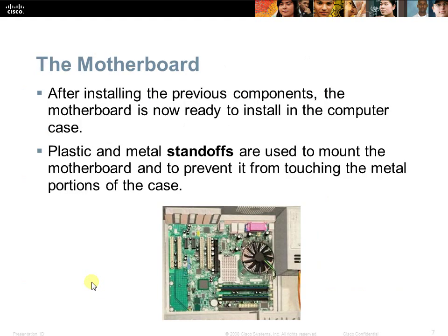The motherboard itself. So when you have all the components installed, you're going to put it in the case. You want to make sure that it sits on the metal standoffs or plastic ones. Sometimes they're plastic or metal, and you want to use the appropriate amount for your form factor and your particular motherboard. Just don't cheat and leave a few out. It could affect how your computer runs.